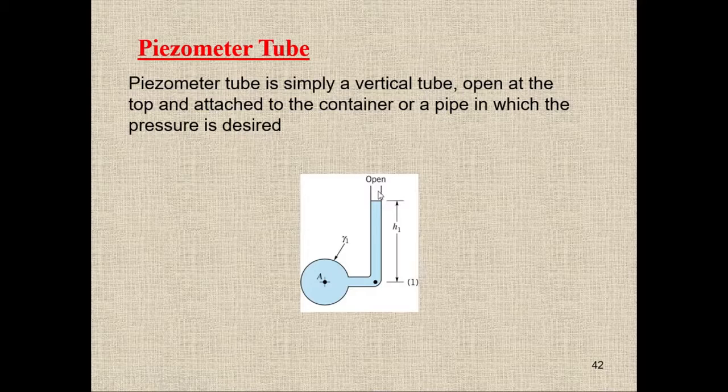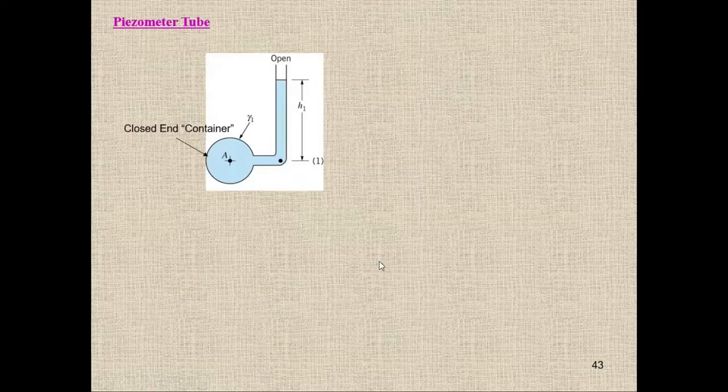Simply, we have the pressure here, which is P atmosphere. So P atmosphere is exerting at this surface, and we have to check the pressure here. Basically we are going downside, so it will be P atmosphere plus, because we are going downside, plus rho gh up to this point. So P atmosphere plus rho gh. You can check again here.